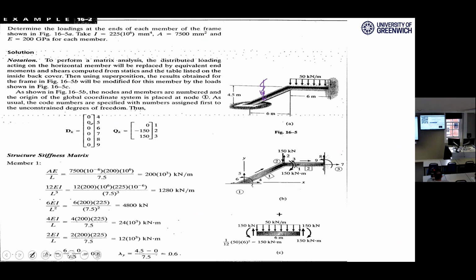We can make an approximation like defining 10 nodes along the element and just put every piece of that distributed load in the associated node. Just divide the distributed load into 10 parts, put each segment in one node, and you will have some sort of element like my structure would be like this, 10 individual concentrated nodes. This is an approximation, and this will significantly increase your stiffness matrix dimension, which is not desirable at all. You will come up with a 100 by 100 stiffness matrix, which is hard to work with.